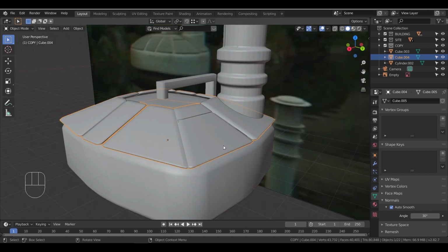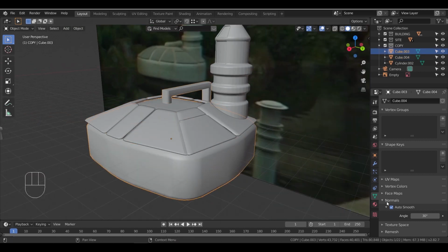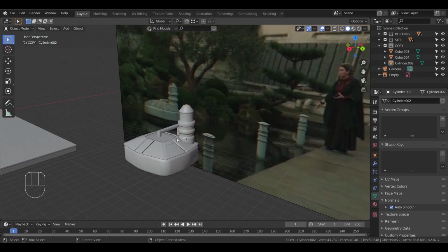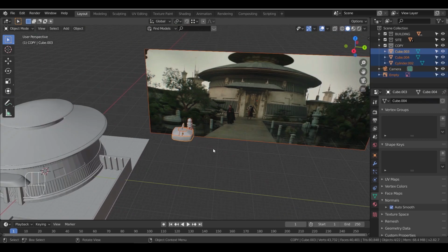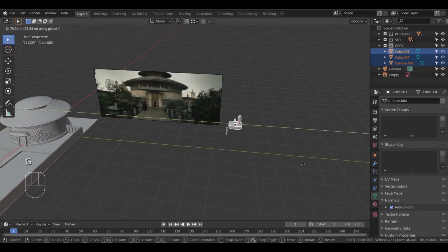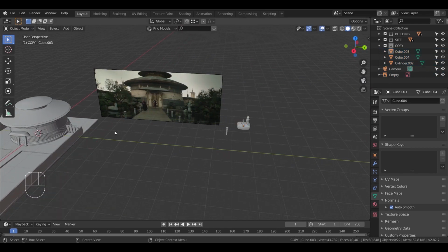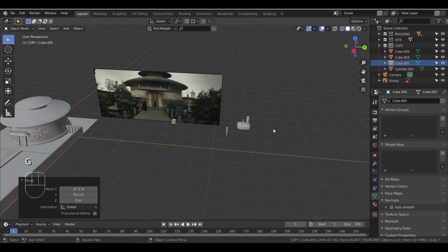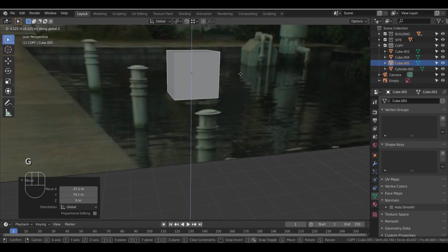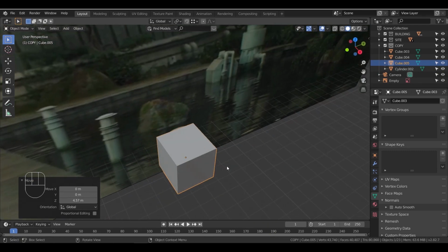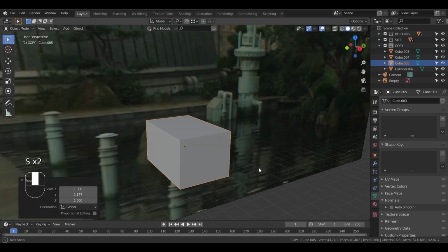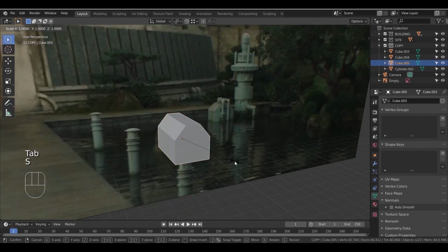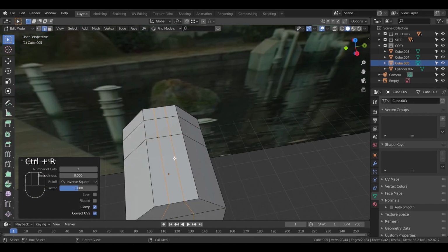Turn on Auto Smooth after applying the smooth shade on the object. Now for this model, we will fast the process a bit. Feel free to slow down the video if you want to check any step, so take your time with it. I will comment if any new step happened.